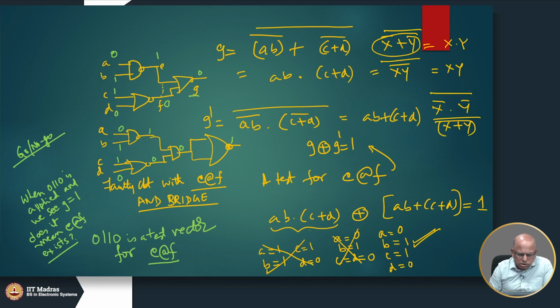The process of going further to find out what could be the reason will require more testing. We may have to apply a number of other tests to start eliminating. We can eliminate, let us say, that G stuck at 1 does not exist, by applying another test. If you have eliminated that, you can now try to eliminate whether E is stuck at 0 and so on.